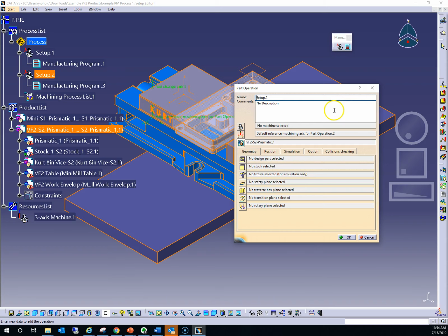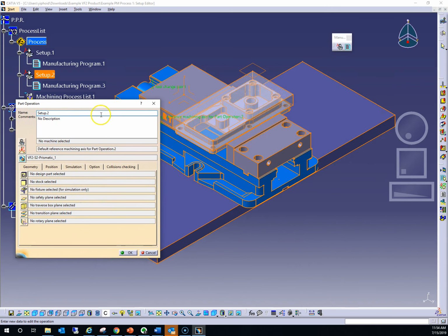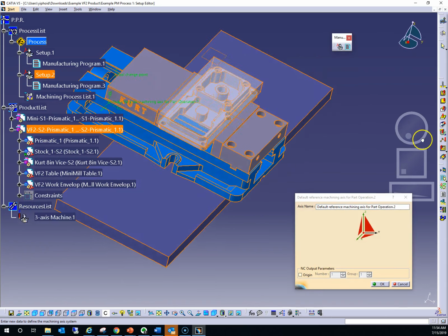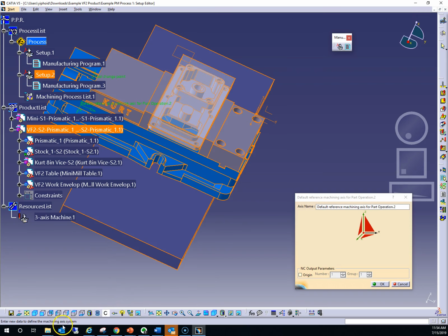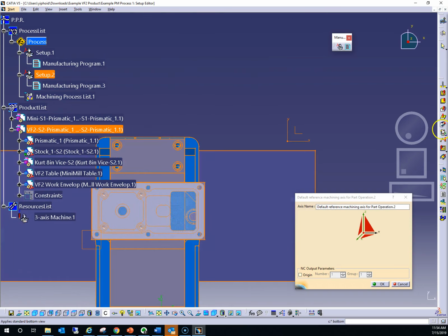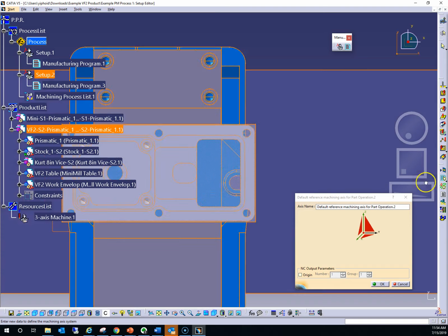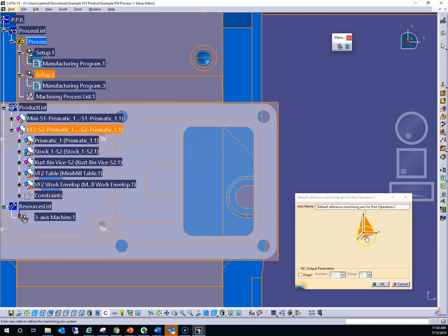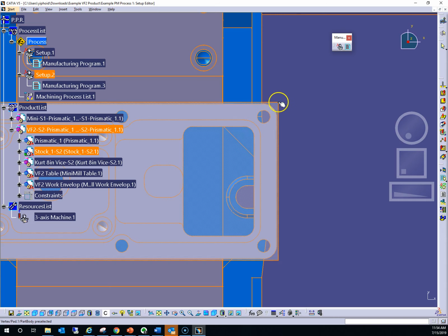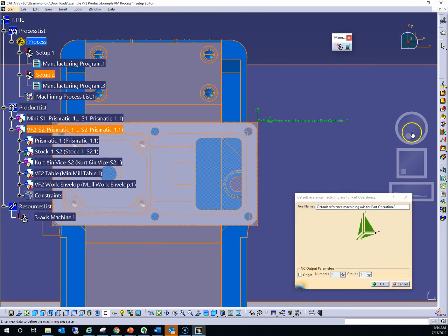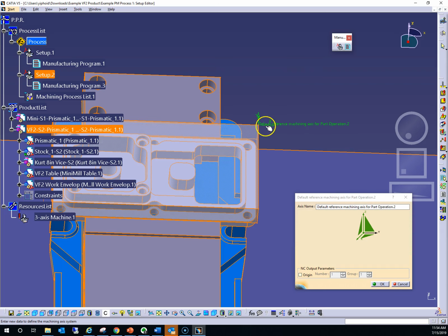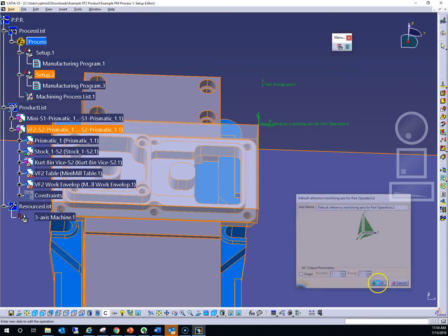So again, for practice, we're just going to repeat what we did for setup 1. Again, starting with setting up the machining coordinate system, which is the second button down. In this case, I'm going to put the display into the top view, confirm that the compass is aligned with the machining coordinate system, so the x-axis to the right, y-axis vertical. And again, using the convention in class, we're going to put the coordinate system on the top right-hand corner. We don't have to change the orientation of the x because it's aligned with the x-axis of the machine. So that's our coordinate system setup.